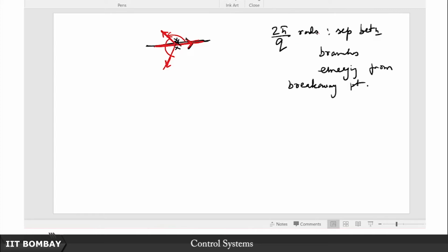And finally we also saw for the root locus how you evaluate if some branches are going from the left half plane to the right half plane, and how you evaluate the points at which this crossover happens. Well, simple, our good old Routh array helps us in that aspect.